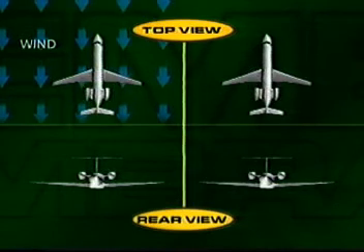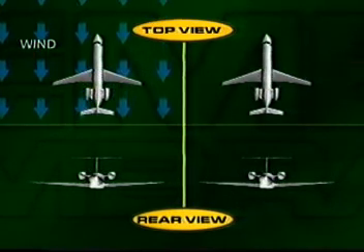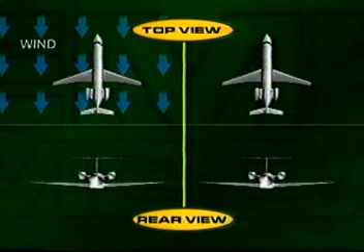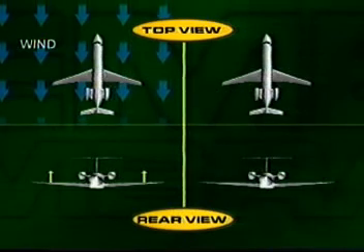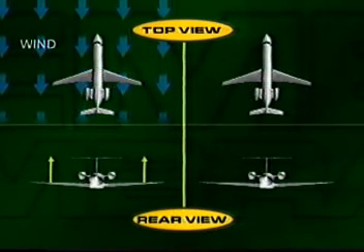If any bank angle is introduced, the consequent side slip causes the wing to roll back to wings level. This is caused by the aircraft sliding toward the lowered wing, which increases its angle of attack, while the other wing has its angle of attack decreased, resulting in a rolling moment approximately proportional to the dihedral angle. Wing sweep also produces a rolling moment due to side slip, caused by the change in relative sweep of the left and right wings. Due to wings being swept in a high-speed jet, the effect is normally stronger than in turboprop aircraft. See how it works.